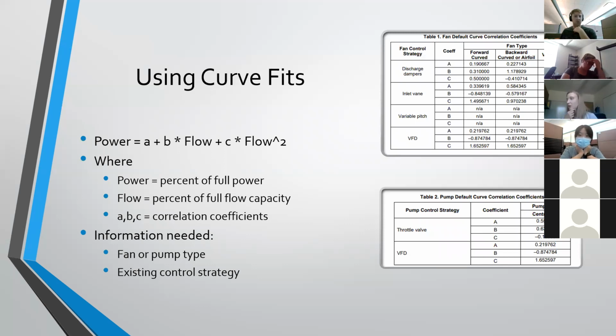You can even use this to estimate your original power draw if you don't have the information to use the pump power equation, or that measured amp data. This is another way that you can estimate your baseline energy usage, but it also has these VFD curves.